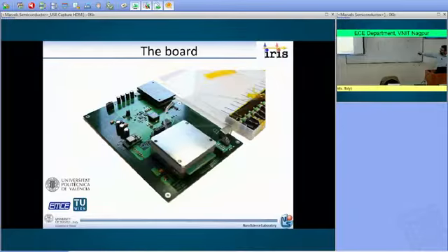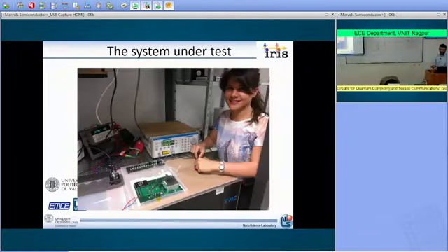And here you have some microprocessors that are used in order to address the different routing protocol that you want to implement. And then you take the circuit to the lab where you have a tunable laser that provides you the input optical signal, and then you have a photodetector that allows you to measure what is coming through your optical network.